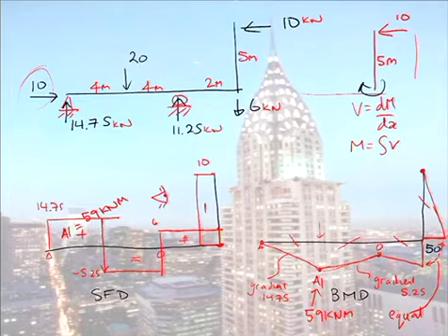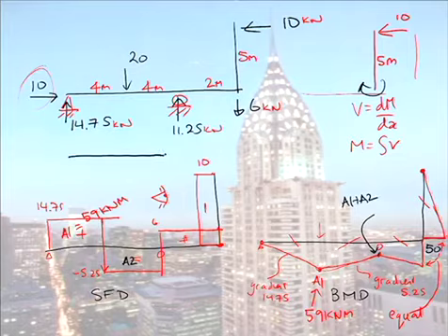Now with this third point here, that value of moment there, well, it's just A1 plus A2. And because A2 is a negative area, it would give you that value. Or I personally don't like using the area method when things get too complicated. So what I would simply do is I would cut the beam at 8 metres. It's personal preference.